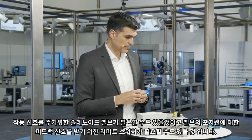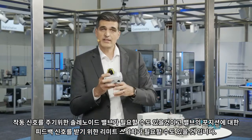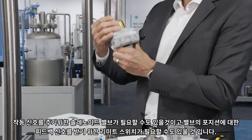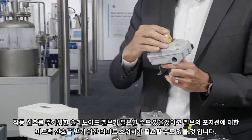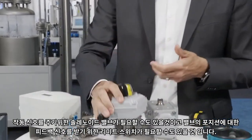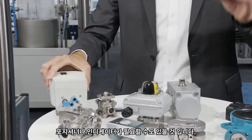Once you are able to assemble the unit, you start with the periphery. Do you need for your application a pilot valve for the operation, a limit switch box for having the feedback signal about the position of the process valve or even the electrical feedback signal? Do you need positioners or optical indicators?